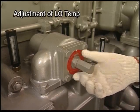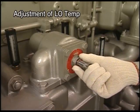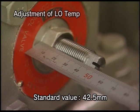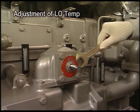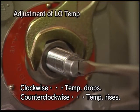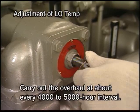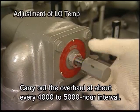Remove the cap nut, measure the position of the adjusting bolt, and check the valve. After the check, loosen the lock nut, turn the adjusting bolt, and adjust the temperature. After the adjustment, tighten the lock nut, fit the cap nut, and the work will be completed.